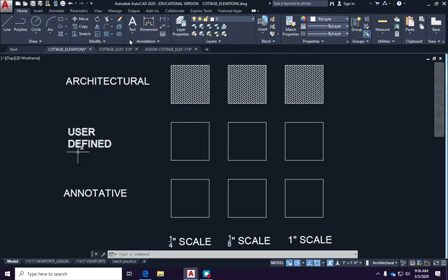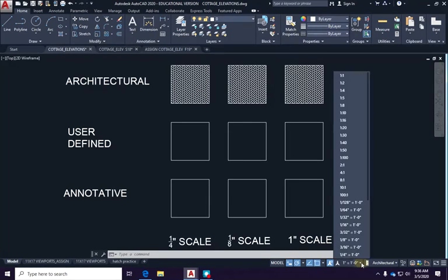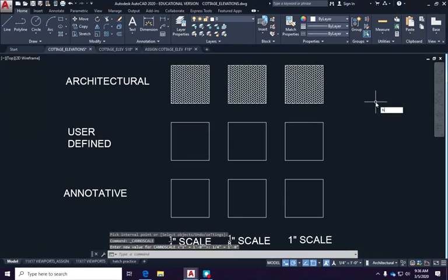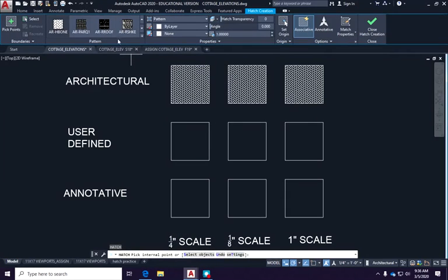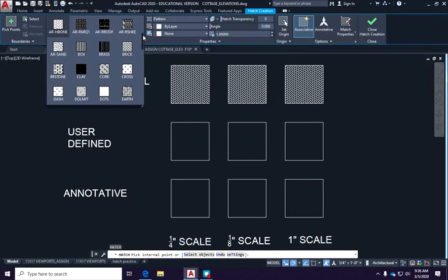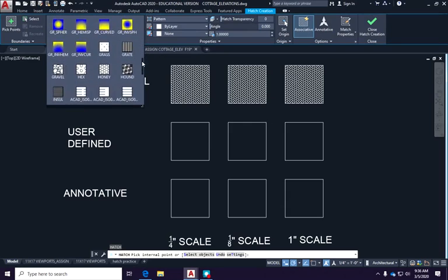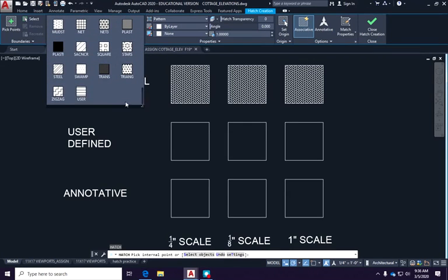We're going to switch to a user-defined hatch right now, and this is the one I use for siding. And anything, you can use this if you're doing Doug's projects where you've got board and batten siding, I can show you how to do that as well. So I'm going to switch back to 1/4 inch scale. H for hatch. And when I go over here to pattern and click the down arrow, scroll all the way, it's the absolute last hatch. He is the user-defined hatch.